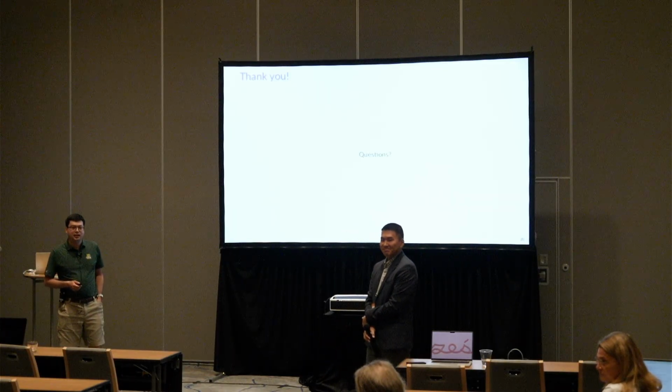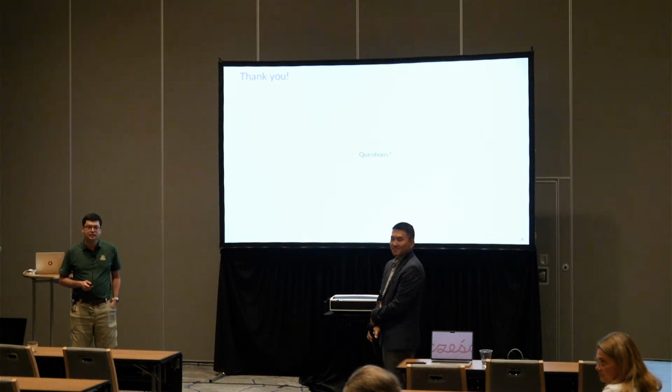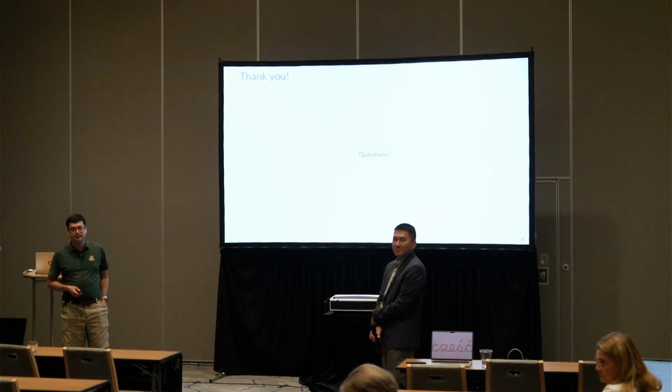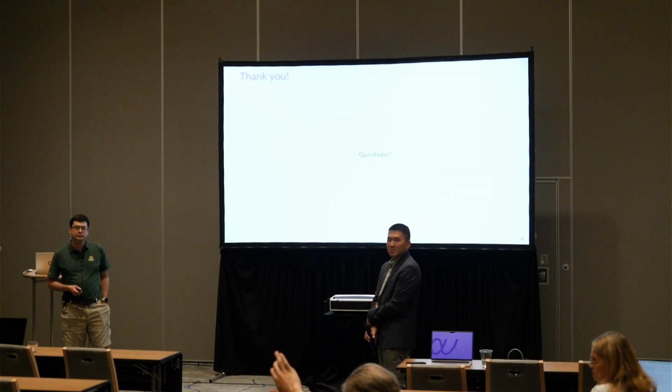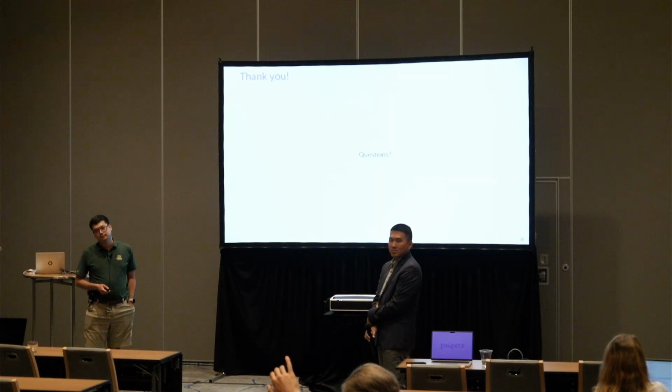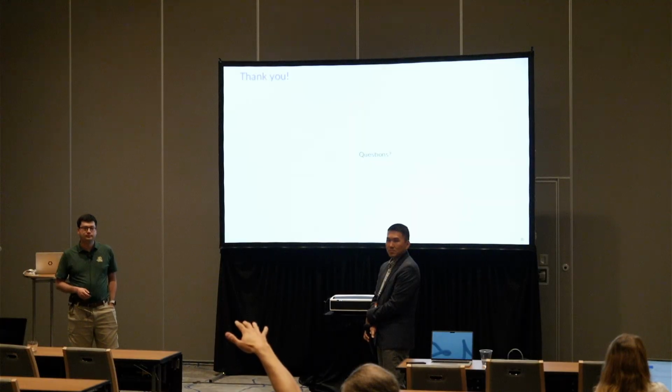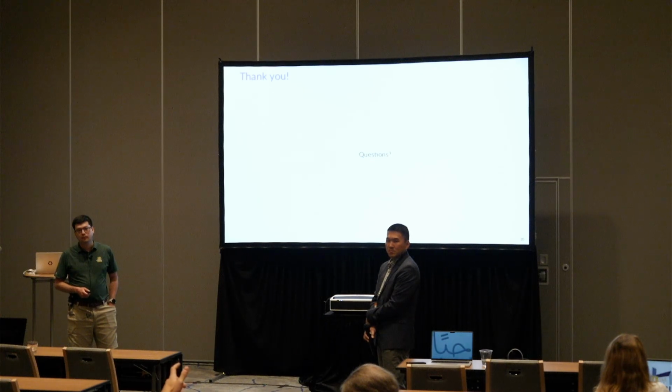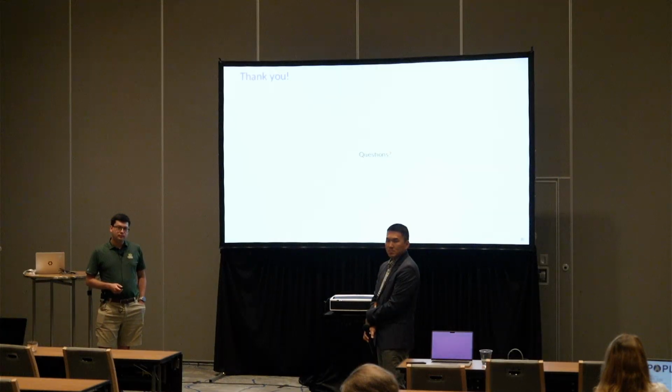The first thing that came to my mind is VLIW with stop bits, something like Itanium where you can compress no-ops. I'd be curious, specifically talking about iCache fetch, one thing about having a contiguous instruction stream of bundles is that your memory width response is going to be like 512 bits. If you have a bunch of contiguous bundles, you'll have an easier time filling that compared to having 4 lanes and needing to find 4 separate 512-bit fetches, unless you're doing fetch fusion without control flow divergence. Does this make sense? It might be easier to have better iCache behavior with a contiguous instruction stream rather than 4 independent ones?